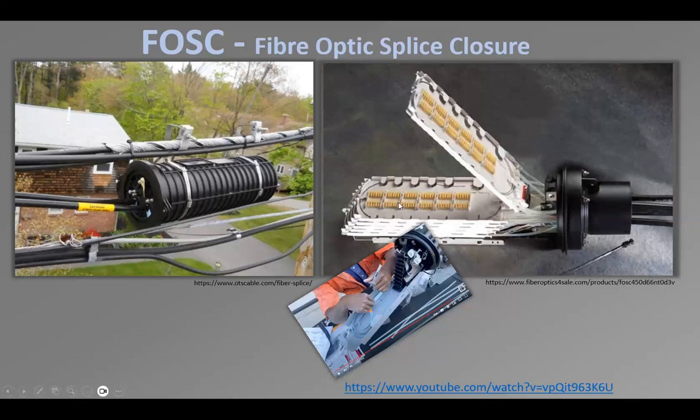Now, fusion splicing, like I said, those strands are fusion spliced. Fusion splicing, and we're going to do that in our lab, is basically taking one strand of the fiber optic and putting it against another, like butt splicing, and it has to be nicely cleaved, which means they both need to be cut to a straight edge. Then they're aligned, so the cores align and the claddings align, and an electric spark is shot at the point where they touch. It's almost like spot welding glass, but this is called fusion splicing. So now you know what these are.